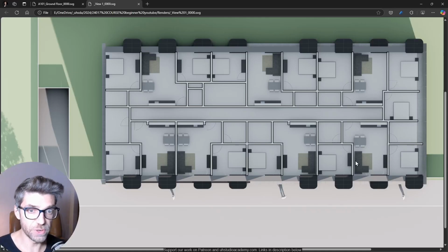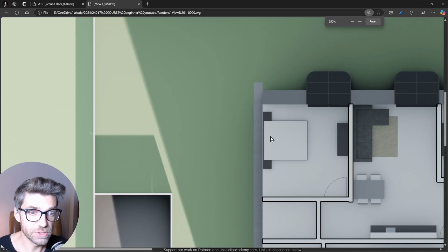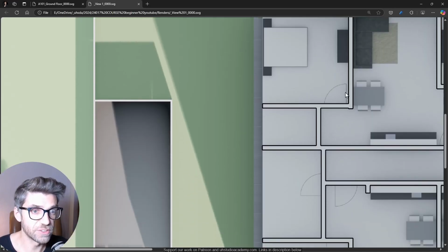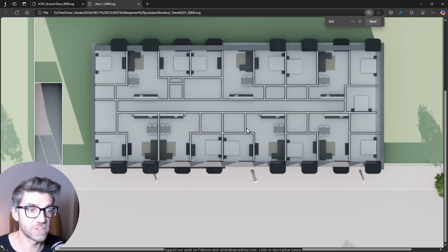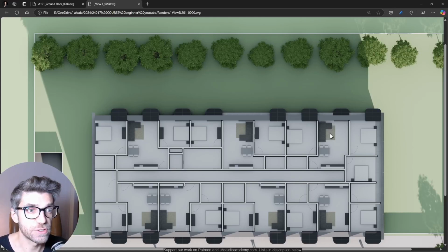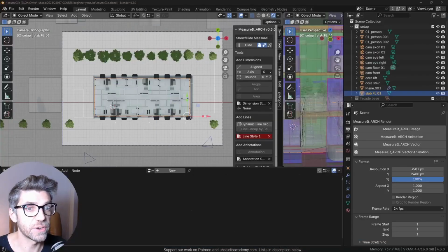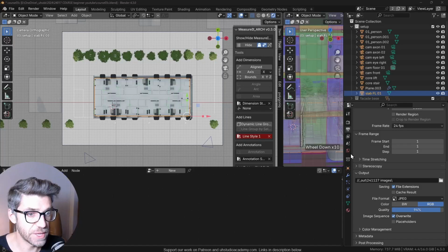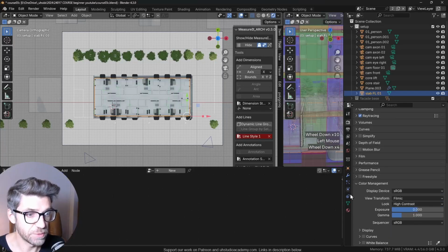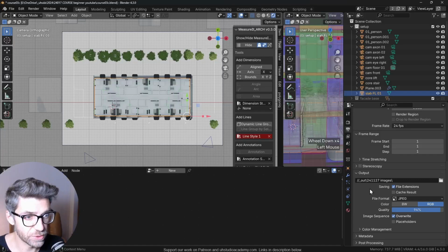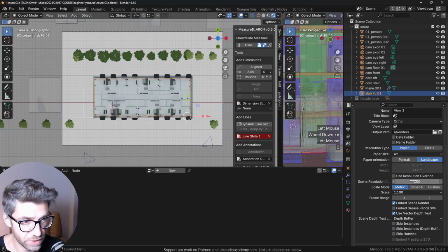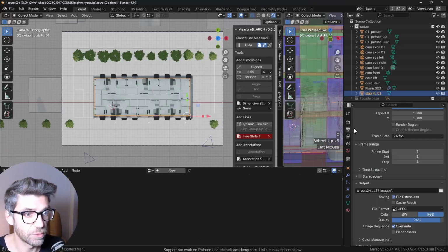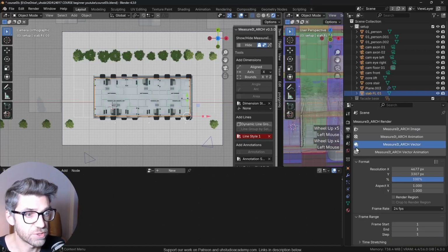Of course, we can further modify this. Now, because our doors are actually not vector data, they're not looking as nice and as smooth as the rest of it. And we're using 150 DPI where our floor plan is not terribly big. So we can go in here and let's try making this higher DPI, maybe not 200% because that's 4 times as big, but we're going to try and do it with 200 DPI. See if that's going to be a bit cleaner. And now I'm going back into here and measure it arc vector.